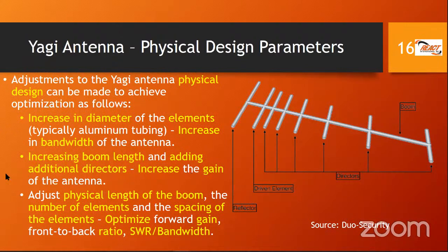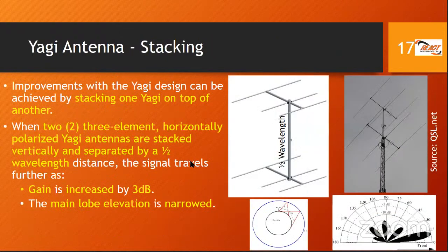So you don't always have to drive more power from a transmitter. You don't have to say, okay, I'm running 100 watts, let me run my legal limit, 1.5 kilowatts, whatever the authority, FCC or TAT, whoever gave you that permission. But in hams, we say run only as much power as necessary. So you don't have to drive power alone to get your effective radiated power up. You can use these antennas with gain and throw your signal a little further using less electrical energy, but you're optimizing with your antenna. And that's what you're doing when you use directional antennas.